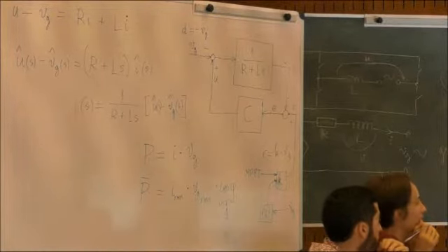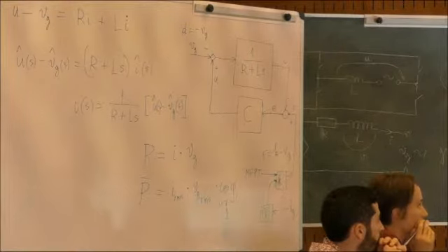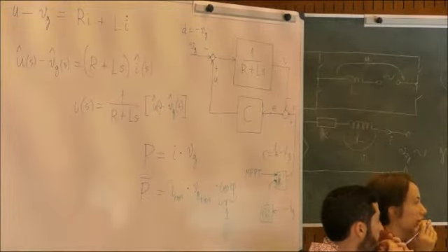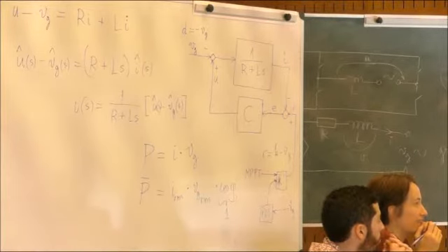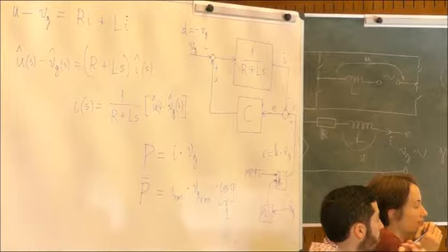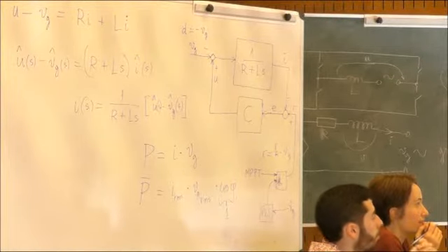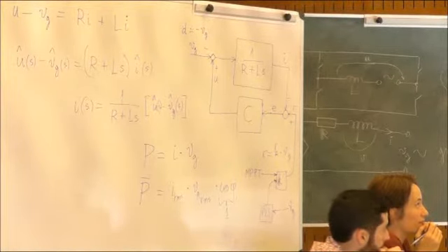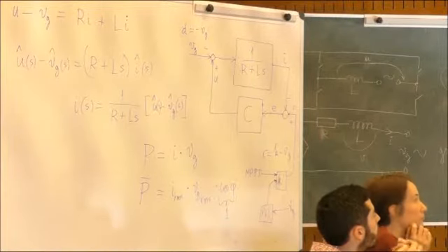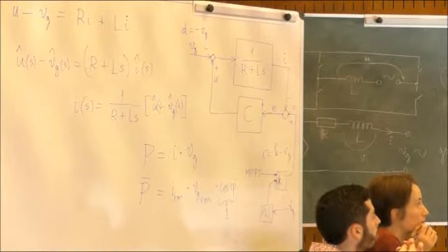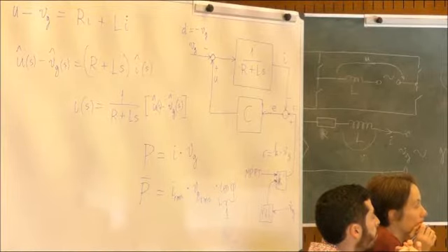Yeah, they vibrate. Okay, now that's not a good example, because then it means that this vibration is internally generated. It is part of the dynamics of the system, and when you act on the system, the frequency of it will change, or hopefully it will disappear completely, right? So it is an internal mode, maybe not an instability, but close to instability, because probably it's damped oscillations, right? It is a mode close to the imaginary axis, but it is part of your system, it is part of the plant.